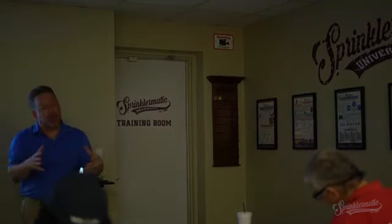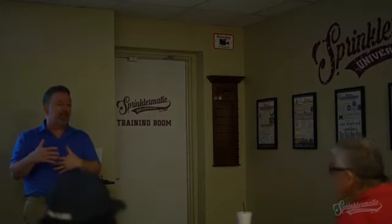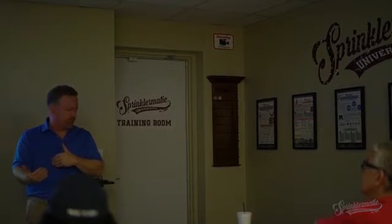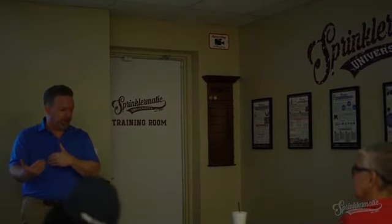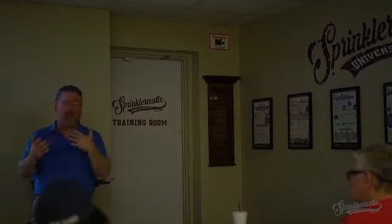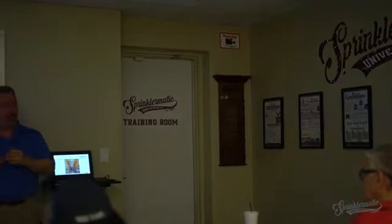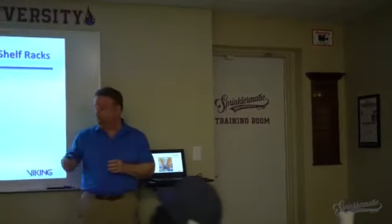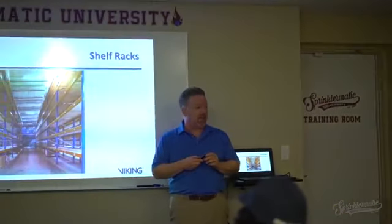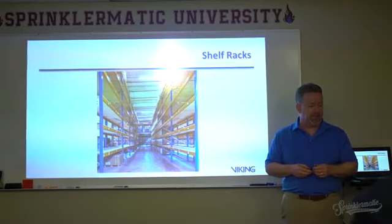So basically, what we're doing here is, typically when I have solid shelves, you're going to wind up with in-rack sprinklers in those locations. There may be times when there may be designs that are using those shelves as barriers and intended to be there. But yeah, a solid shelf, you're going to wind up with in-rack sprinklers. If you don't see in-rack sprinklers in a situation like this, that's a red flag. Find out, consult with the designer, what the design was intended to be.